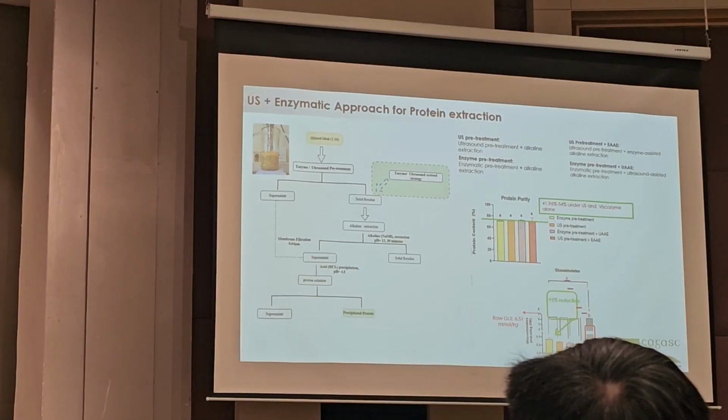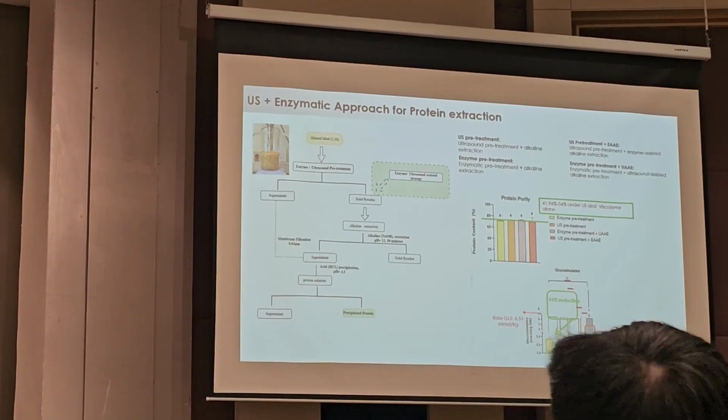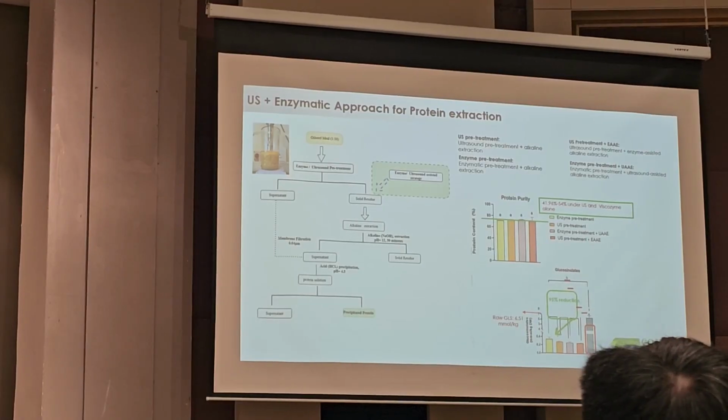When we add yeast to any fermentation media, it goes as a clog. When you give ultrasonics, it disperses that yeast to improve the surface biomass. Otherwise, because of cavitation, it causes pores on the bacterial cells or microbial cells, helping substrate to go in and product to come out. So that all has been well established.